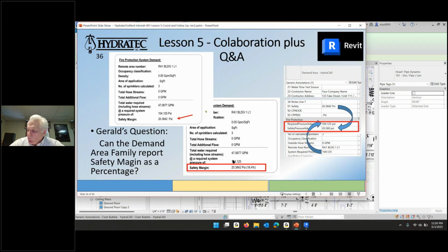And Revit, unlike some more robust programming languages, doesn't have a convert-this-text-to-a-number function so that I can do math with it. I'm hanging my head in shame that we did that. It's a number. Why didn't we send it as a number? I think we were trying to get the formatting to work out better. So we said, let's do the formatting, and then the number won't move to the left or the right or the middle. It'll just be where we want to put it.